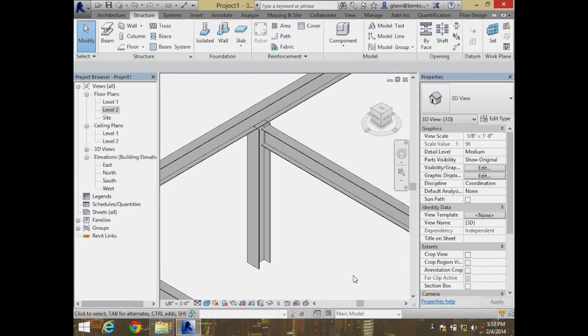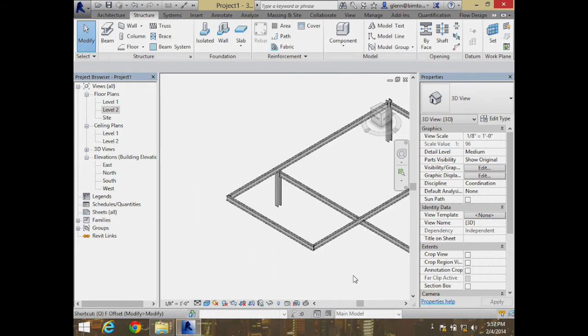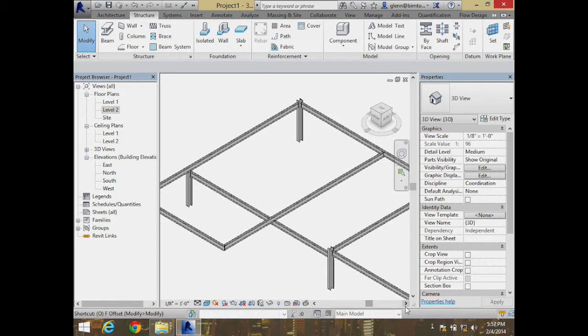Okay. In the beam itself, they weld some plates right in here so that we have a nice square connection to transfer the flange loads, and then we place the next column on top of it. Okay. So that'll work out okay. Good question, because that's actually the weirdest connection in this right now. So once we've got that, we're ready to start thinking about how we can frame in the other direction.